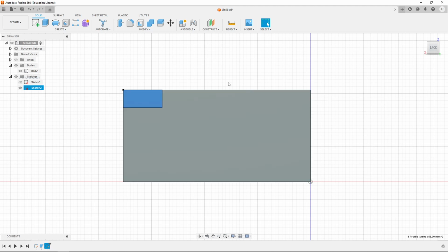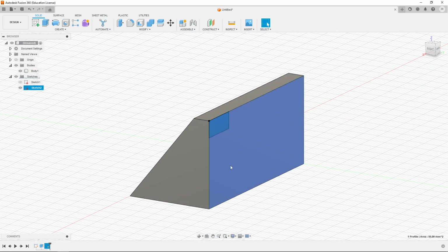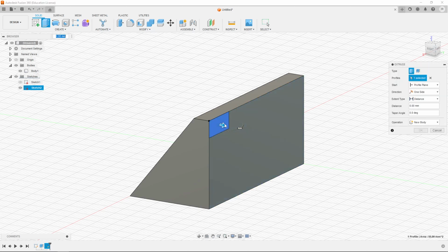And again, I'm going to change my view just so we can see it as it happens. It's really nice to see in 3D. I'm going to select my extrusion tool. Notice the default is backwards. I'm just going to drag it so we can see what happens. If I pull back, the implication is I'm making a rectangular box that pulls off from the back. And then these would be merged into one body, but I want the opposite. I want it to be scooped out going forward.